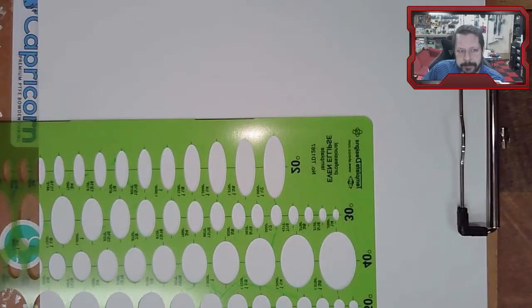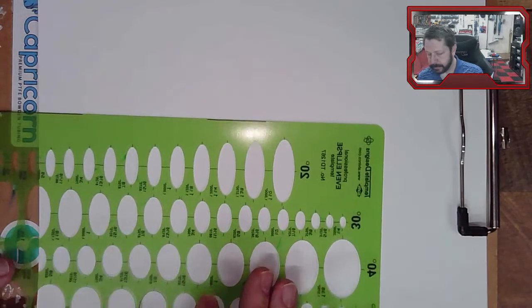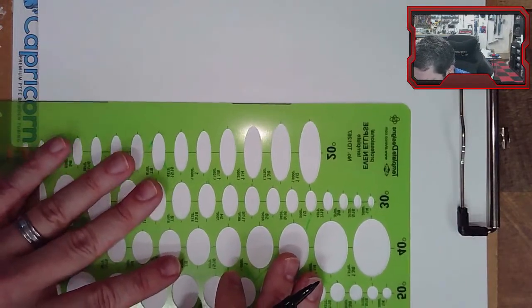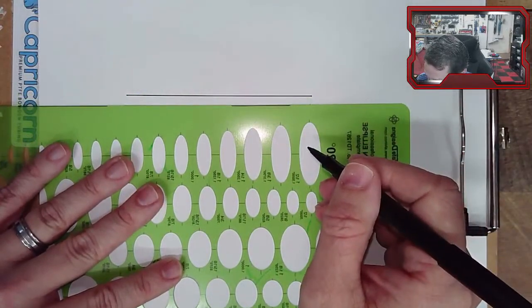I will say that this is assuming the shaft itself can be at least approximated by a straight shaft. It doesn't have steps in it or anything. Once you start adding steps in larger sections to the shaft, then you may even have to treat those as extra weights, which are distributed, which is a little weird. So this will give you an approximation. It won't be exactly what you could calculate in a numerical solution of some sort.